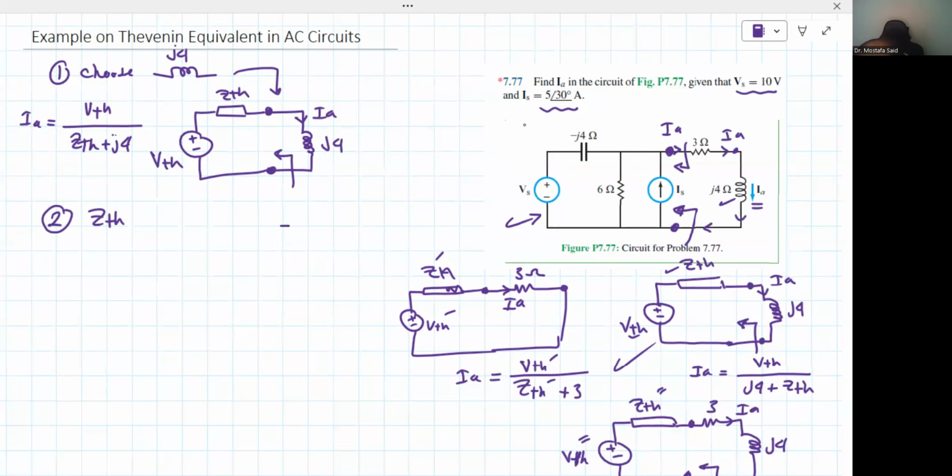So these are the two terminals of the inductor. We remove the inductor completely and we put a source called Vx that produces a current called Ix. Good. Then we cancel any independent source. Very important. Independent source. Luckily, in that circuit, we have two sources, a current source and a voltage source, and both are constants. Both are independent.